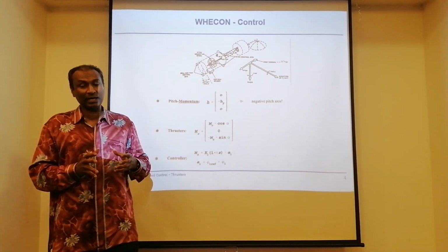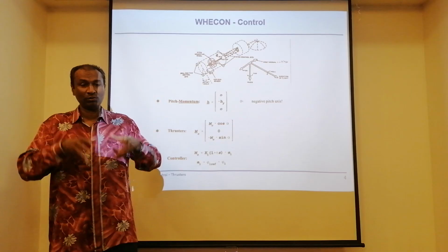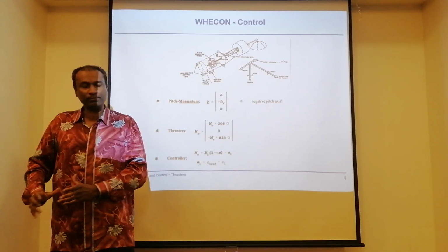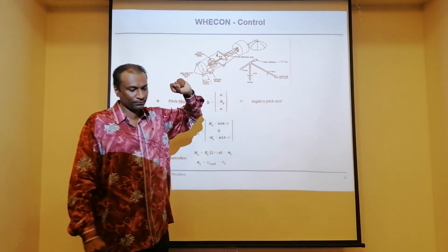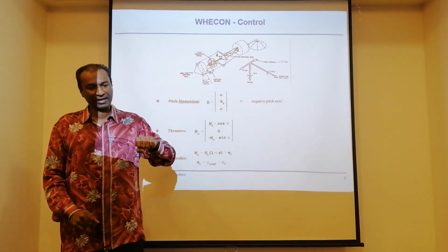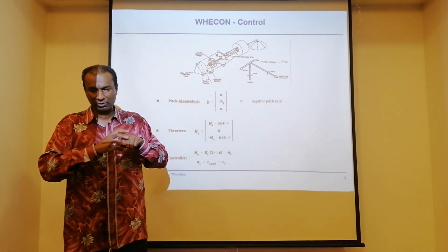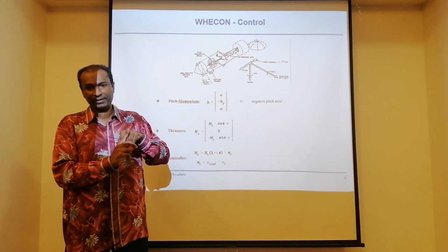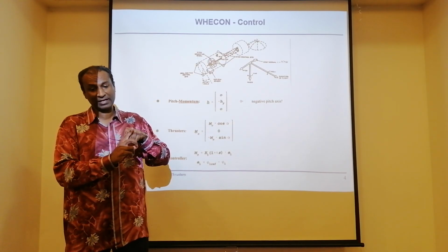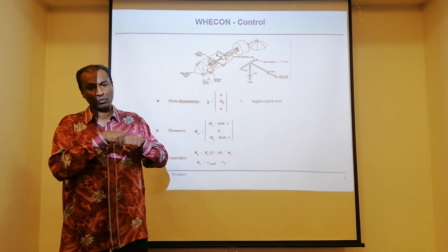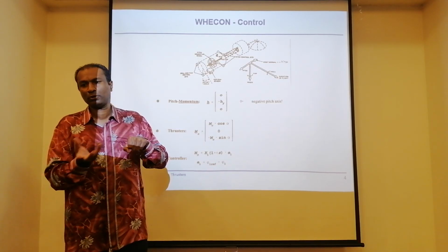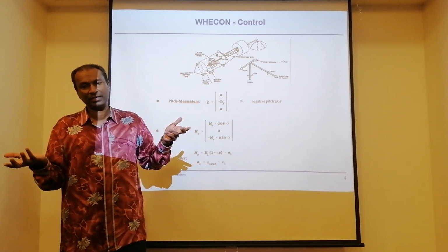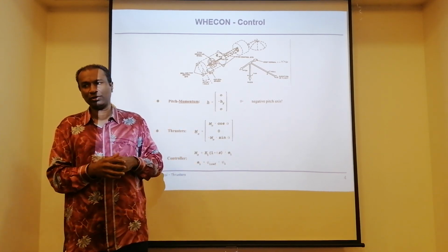That means I give a negative torque so that the wheel speed actually slows down. In order for me to get a negative torque, let's say this is a cylindrical body, I fire the thruster system. I fire, let's say, 1 Newton up and 1 Newton down. This body is going to rotate. Depending on a positive or negative rotation, you can have a rotational motion in order to desaturate the momentum wheel.